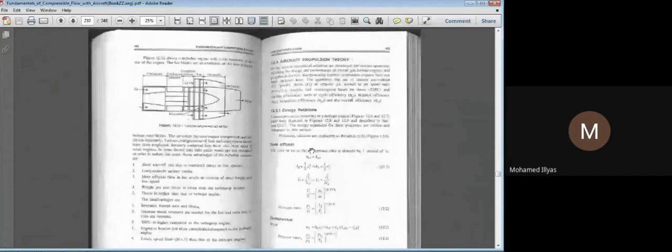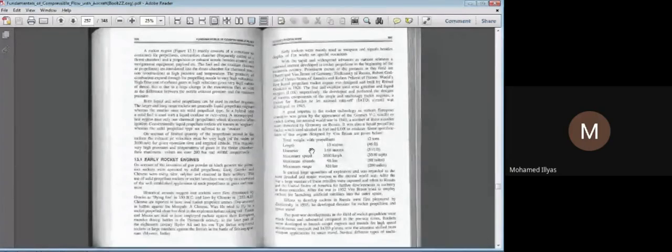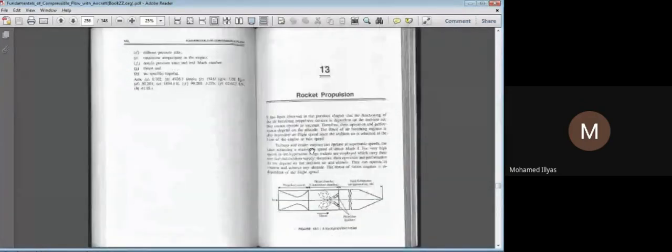Okay, so I can show you here. If you see our diagram, it is one of a liquid propellant rocket. You see this convergent divergent nozzle. If suppose the velocity is decreasing in the divergent nozzle, they will not use this. The velocity has to increase because we need a very high velocity. Correspondingly, we will get a thrust force. So that only is used to give propelling the nozzle. So you have a convergent divergent nozzle there.